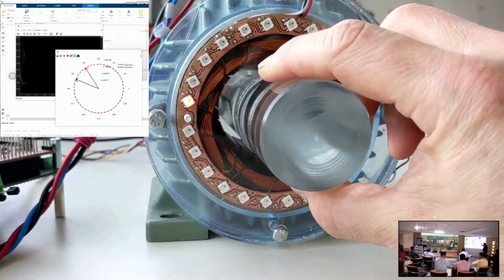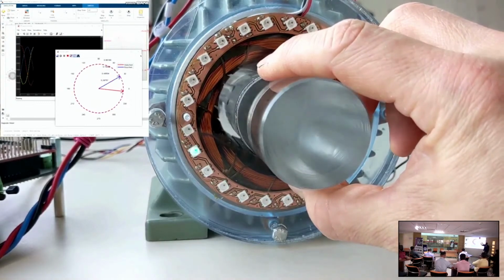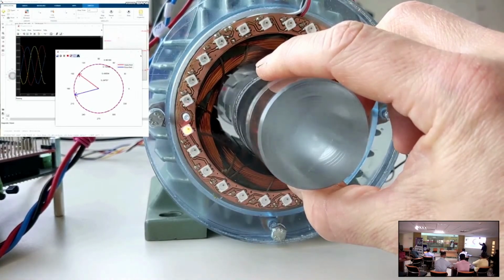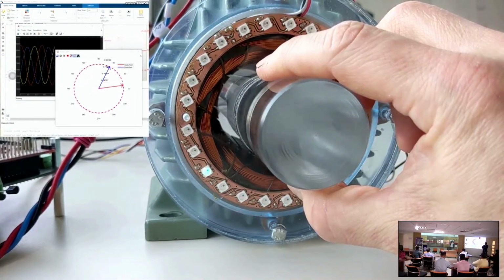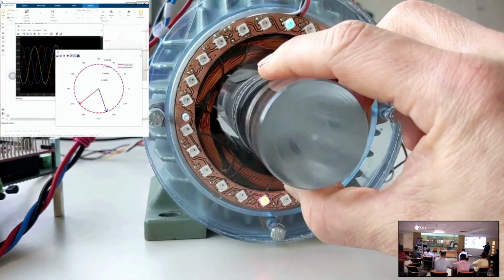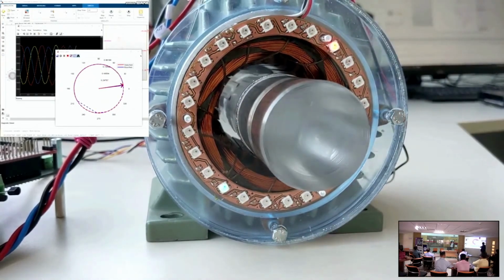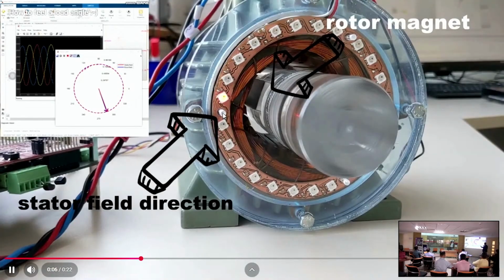Now he is trying to slow down the rotor by applying physical force. Trying to slow, not completely. That is now loading. Load. He is trying to slow down. Now the rotor definitely cannot always be aligned with the stator field. It tries to align, but it will lag. That is where delta comes into the picture. Here is the delta. Now he showed that again, revise. Back. One small observation, but yet effective.